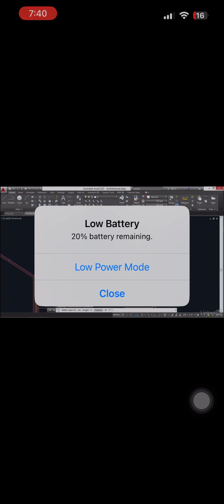It says specify new length. I'd like to snap that right here. So I'm going to hold down Shift, right click, and choose endpoint. And I'll snap that right there. So now the table is perfectly scaled so that it matches the width of the sofa. And I got AutoCAD to figure out the scale factor for me by choosing the reference length and then the new length. Now I can move the table over into the space, and I'll use ortho by pressing F8